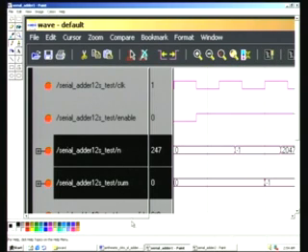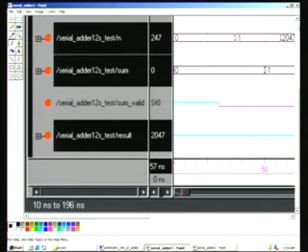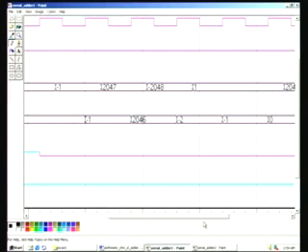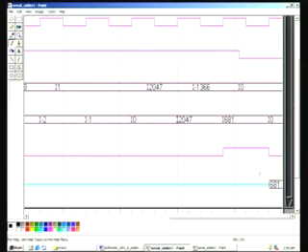Here you can see that clock, enable, n, sum are all applied here, and this is the final result here. This is the first set of inputs. 0 is applied, then -1, 2047 and so on. You remember -1 was triple F there, and here it is the final result. 0 minus 1 is -1, -1 plus 2047 is 2046, and keep on adding like this. Finally, for the entire set you would have done.